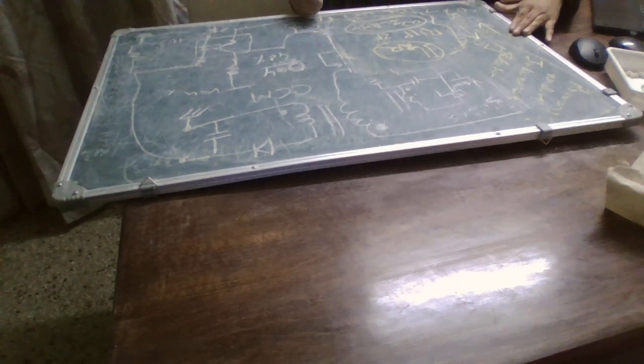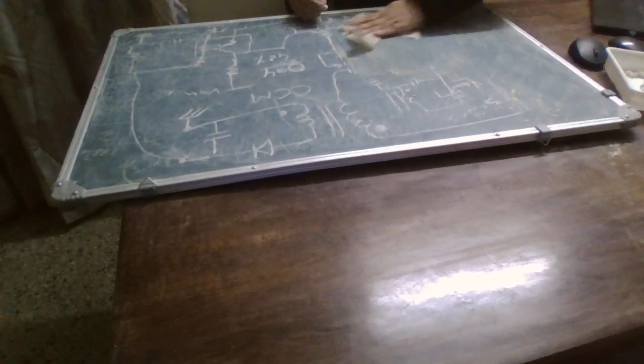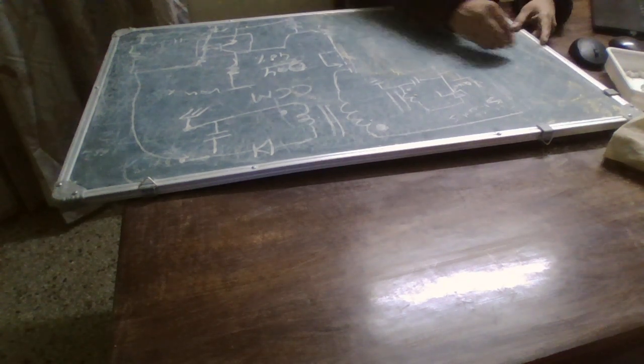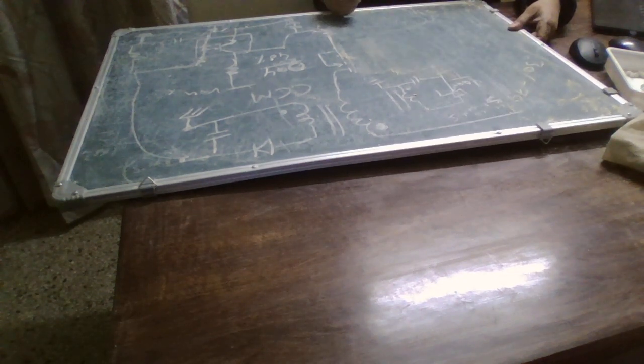So a maximum ripple ratio is going to be between 30% to 70%, and it gives us a good balance of the total power loss of the transformer, matching the downslope of the transformer current to the internal slope compensation, and increasing the right half plane zero frequency.